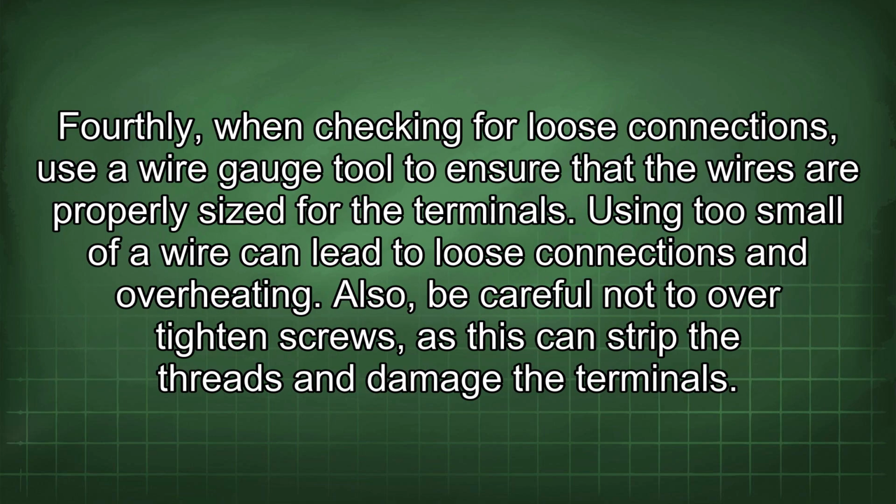Fourthly, when checking for loose connections, use a wire gauge tool to ensure that the wires are properly sized for the terminals. Using too small of a wire can lead to loose connections and overheating. Also, be careful not to over-tighten screws, as this can strip the threads and damage the terminals.